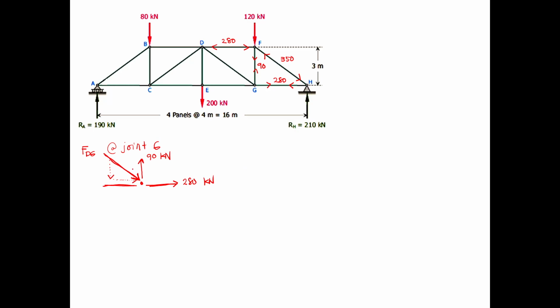Okay, so also notice that these are the same triangles. So it is proportional 3, 4, 5, or the angle. So the angle for this one is the same as this one here. So it's still 36.87. So in shortcut, if you are already quick with your trigo, upon drawing the force triangle, this one is FDG.